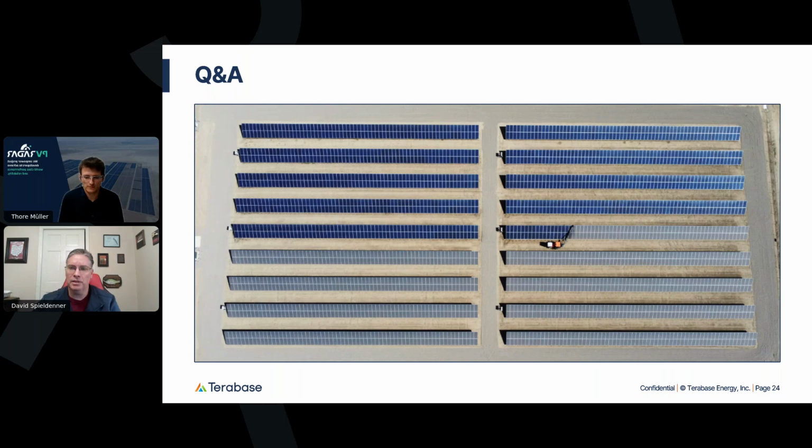All right, somebody was paying really close attention to your demo because they pointed out in the cleaning simulations, why doesn't the soiling level go to 0? Yeah, good question. Depending on the site we're looking at, the PVRADAR model doesn't assume a rain cleaning efficiency of 100%. So even if there's a very strong rain, depending on the intensity of the rain, the soiling for a normal rain wouldn't reach 0. There would still be some residual soiling on your panel, as you would assume.